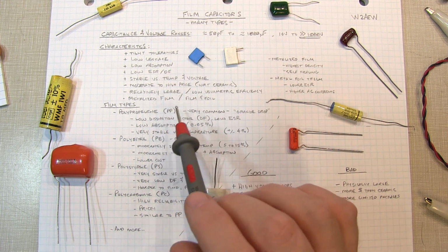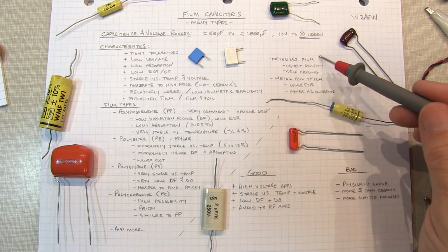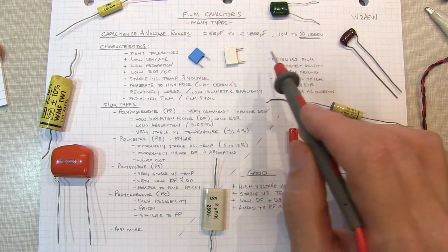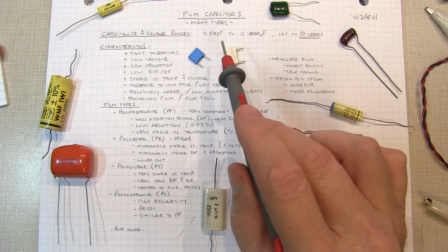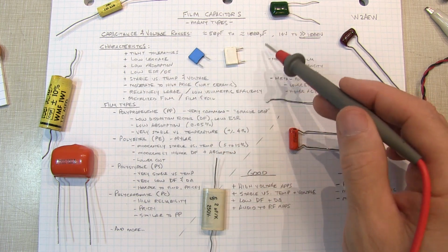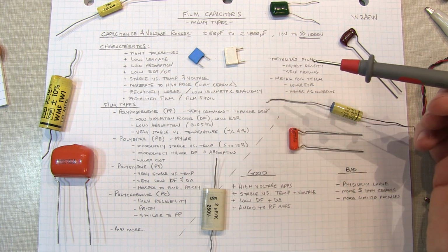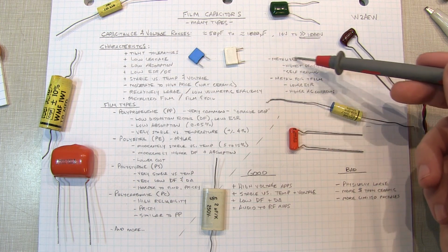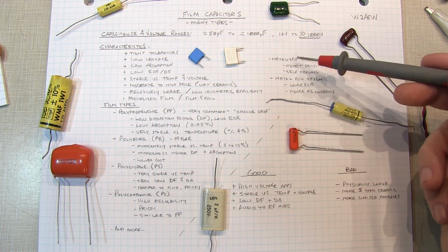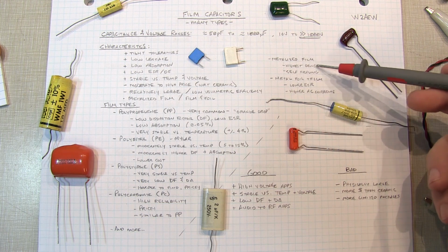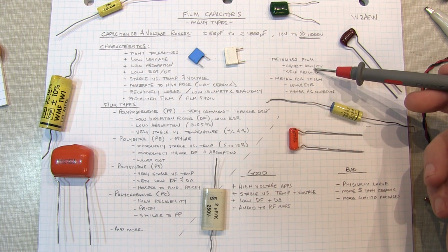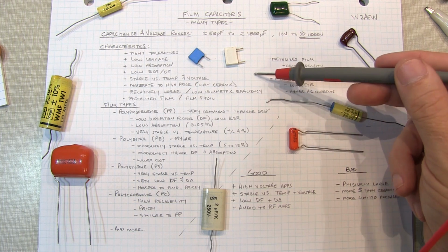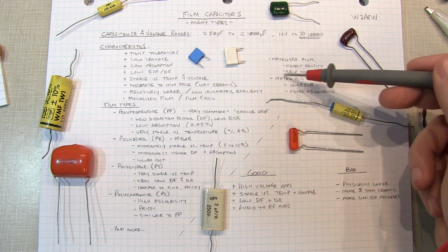They are available in two kind of broad different types. There's a metallized film or metal foil and film. So we talk about film capacitors because what we're talking about is the dielectric material, the insulator between the two plates of the capacitor, is some type of film, plastic type of film typically. And that film can either be metallized on one side and then rolled up, and that's the metallized film capacitors. They've got the highest density because you don't have a separate foil in there. Where the metal foil and film is, you've got alternating layers of plastic insulator, metal foil, plastic insulator, metal foil, and that's rolled up.